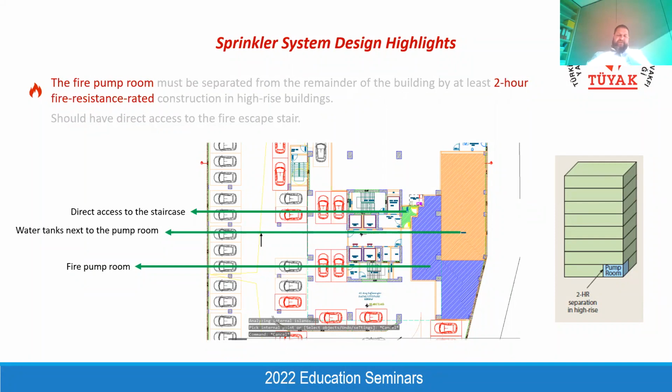That's why when we start the project, first of all, we try to review and check the shaft locations, main mechanical and electrical room locations, and also the location of the water-based suppression system riser, etc. It makes our design very easy to execute because all the shafts and main electrical rooms are already solved and placed, and then we can use the rest of the area as we require from our architectural point of view.